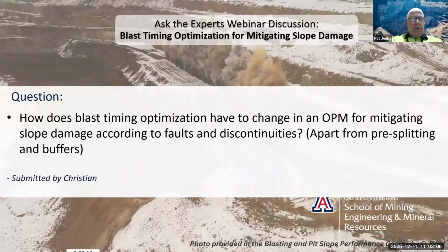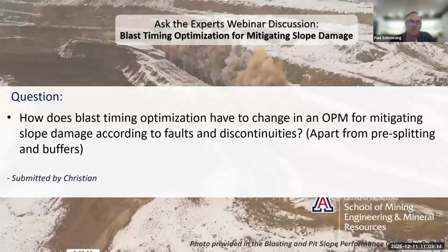So how do we account for discontinuities? Directional shooting. And a lot of times those are good places to have your stop lines, because usually on one side or the other, there's a different timing domain. All right. Easy answer.